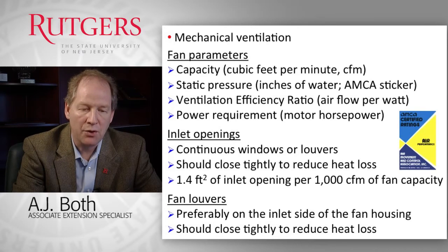The inlets are also critical, and we have different designs. We can have continuous windows that we open up, or we have openings that are louvered. So as soon as the fan comes on, the louvers will tilt open, allowing air to come in.